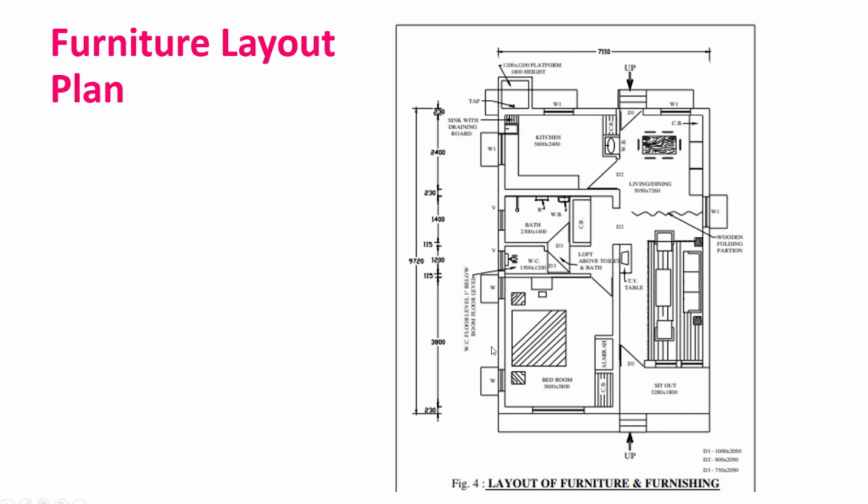There are certain definitions for carpet area and plinth area. As you can see, carpet area is the covered area of the usable room at any floor level excluding the area of the wall. Plinth area is the built up covered area measured at the floor level of the basement or of any story. So these are some basic definitions which many times we need clarification on. Room height we have already covered.